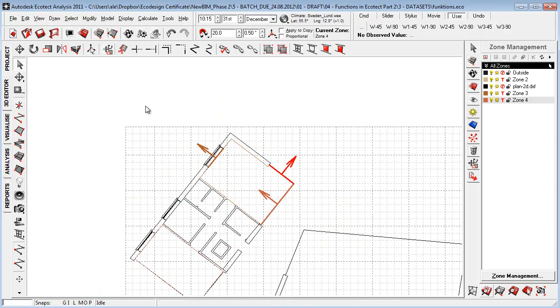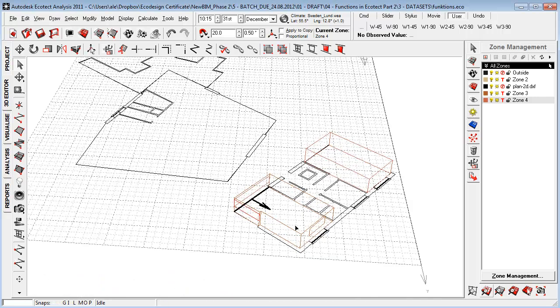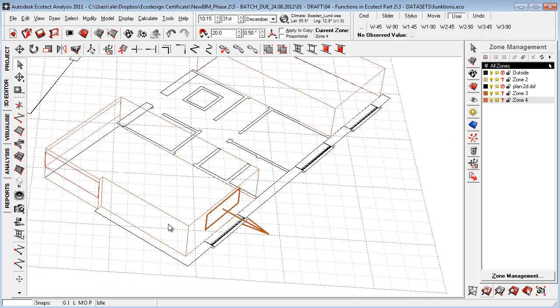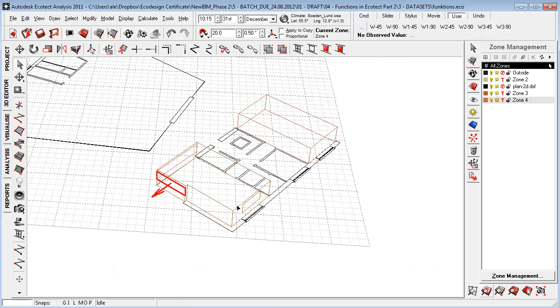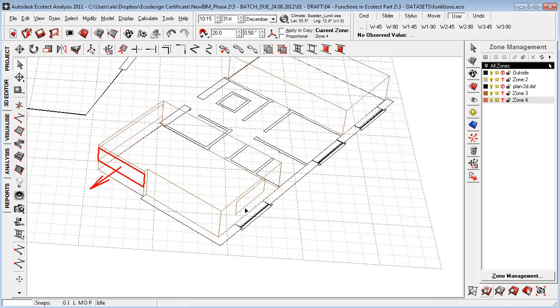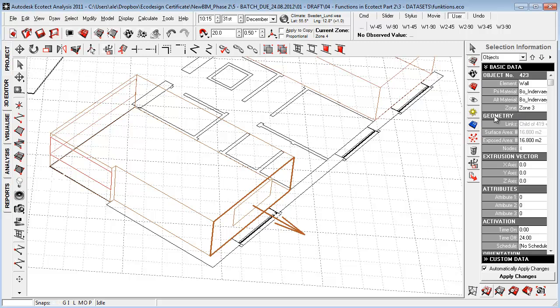One important factor is that when you do this, you'll see that the directional arrow here can be a bit tricky. So remember to mark out the windows and just make sure that they're pointing in the right direction. Another issue modeling this way is that if we hit the wall here and go to the selection information, you see that it's not really understanding the links here.